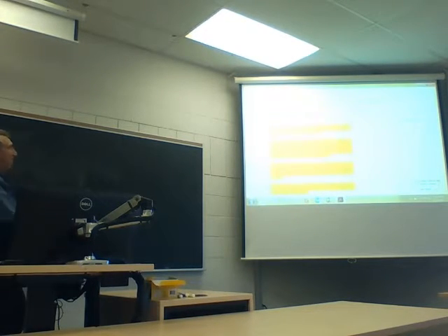All right, let's see if I can dumb it down. This type of compressor is similar in operation and construction to a centrifugal pump. I just said that. It consists of an impeller which rotates at high speed. The impeller is equipped with a number of radial, remember that, or backward curved vanes surrounded by a shroud on one or both front and rear sides. That's probably what we call it.